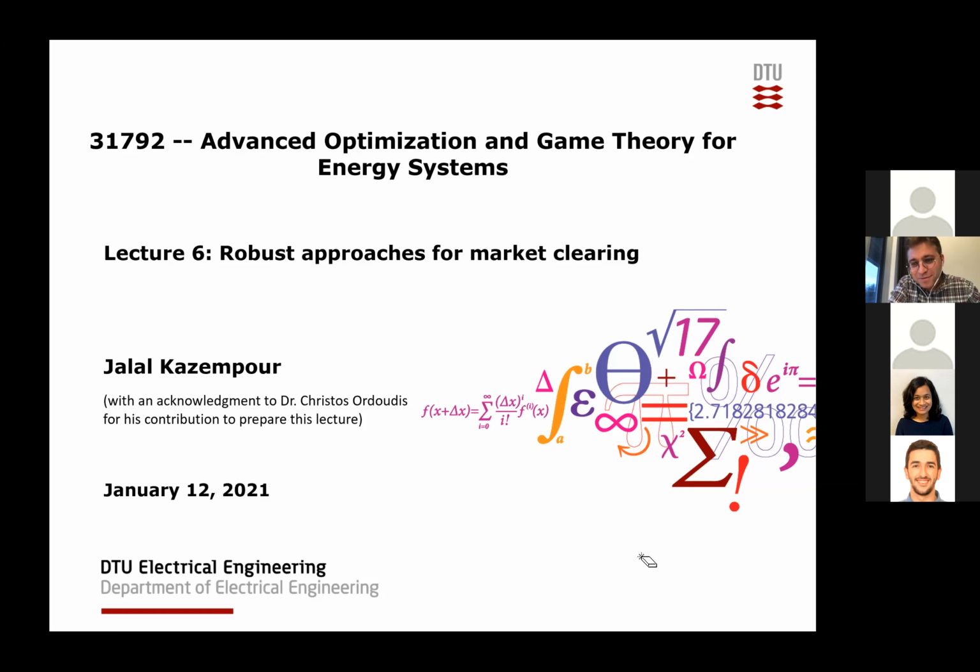Again, I'll use these two abbreviations a lot: DA stands for day ahead and RT stands for real time. Our problem is constrained by production limits, transmission network limits, load shedding limits, spillage limits, and nodal power balance constraints, all of them in day ahead and real time.